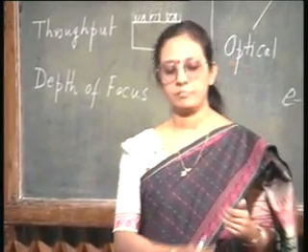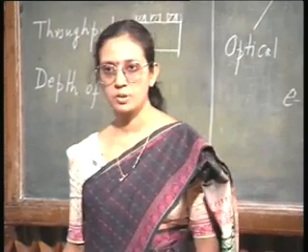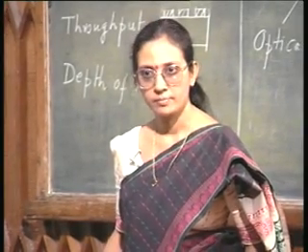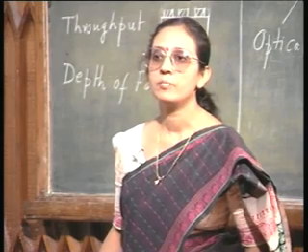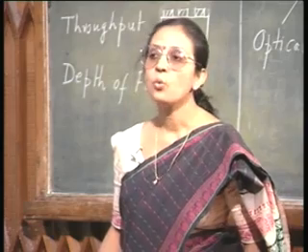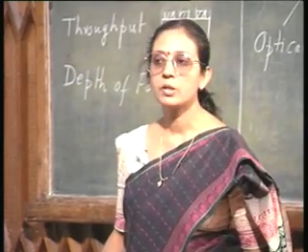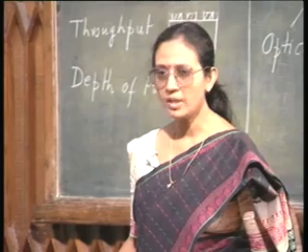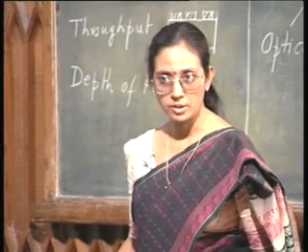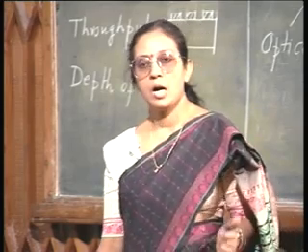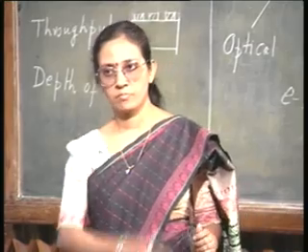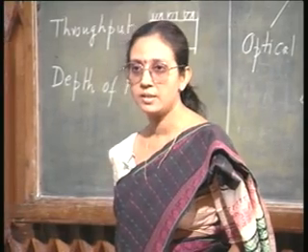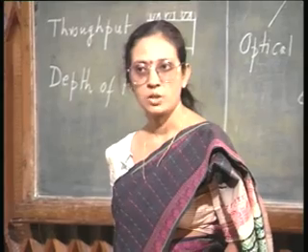And then of course, the first question that comes to the mind is, what do you actually use, optical or E-beam or X-ray? That is where we need to see the relative performance, relative merits and demerits. We will start with the optical lithography, because even now, even today, that remains as the most popular technique of lithography, and it is obviously the oldest technology. In optical lithography, the steps I have already outlined to you. It follows these 4 basic steps. The radiation that we use is UV light.